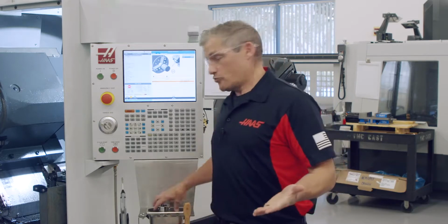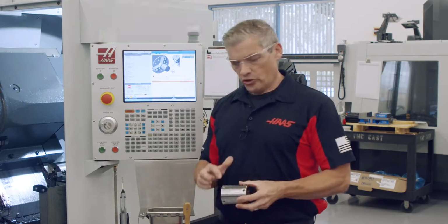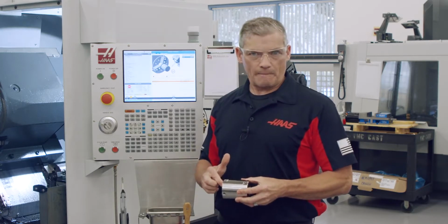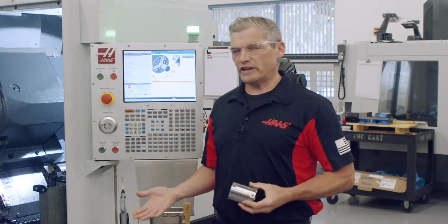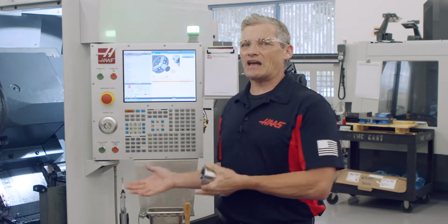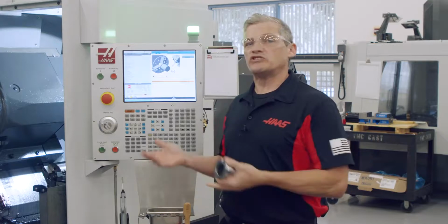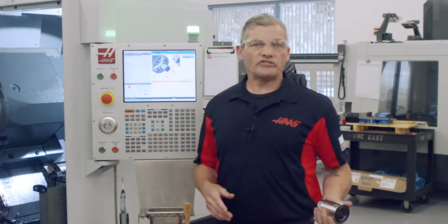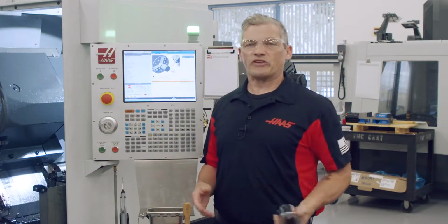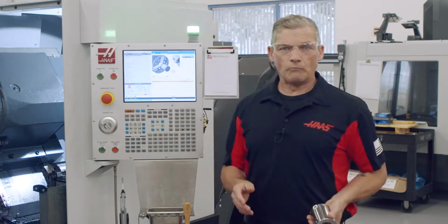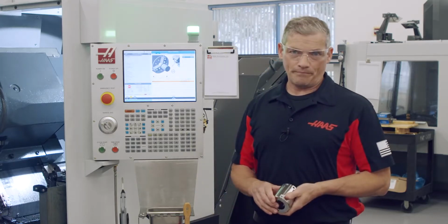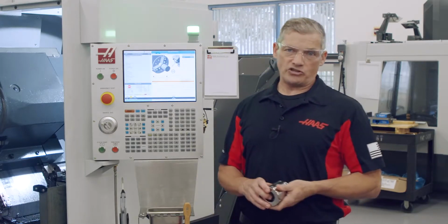Now I want to spot drill each of these 4 holes so the tap will start properly. Making a spot drilling routine in VPS is pretty much exactly the same as the drilling routine we just did, except that you'll be setting a much shallower drill depth for the countersink. So we're not going to bore you with stepping through all of that. Let's move on to the tapping operation.